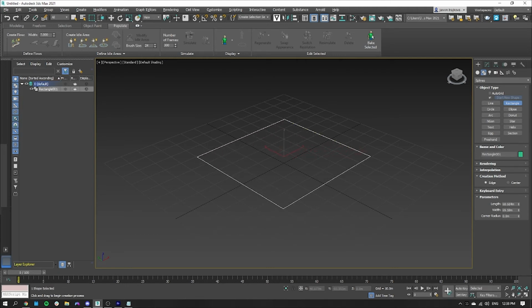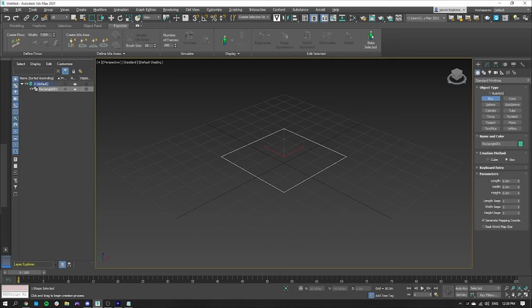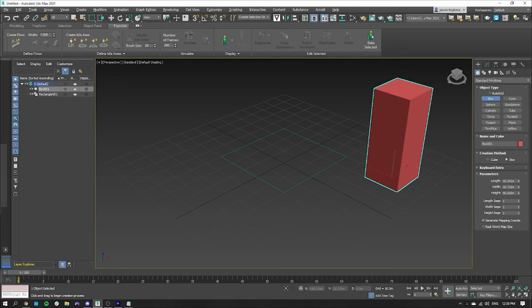If you want to adjust the length and width, you could do it here, pretty instant, and that will create that for you. If you want to do a quick basic 3D geometry of that shape, you click on that, and that will create a box. So you click on this corner, drag, unclick, and then you can lift up or down depending on what height you'd like your box to be at. That will create your height.